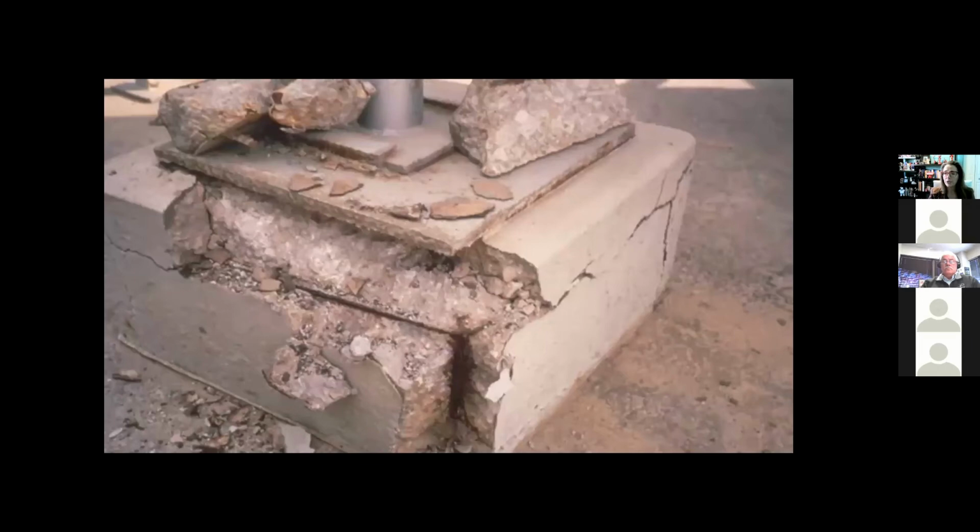What we have here is a flagpole that's showing you some galvanic corrosion. You got an aluminum pole in contact with regular steel. That's going to cause galvanic corrosion, and you can see some of the corrosion in the reinforcement in the bottom section. And you see large chunks of concrete have spalled off here. Now, that's my initial diagnosis when I look at this photo, but I actually know this photo as a freeze-thaw distress and spall. If I also looked at this photo in, say, a parking lot at Walmart or Target, I would think maybe a car hit it. So we don't always know why something's spalled, but obviously this concrete needs some love and repair to keep it in service without having that flagpole tip over.